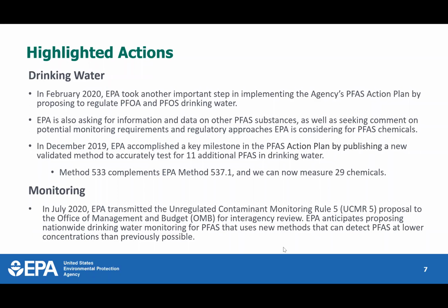Please do. I know a lot of you are water experts, but just as a point of background, the UCMR is under the Safe Drinking Water Act amendments in 1996. It requires that once every 5 years, EPA issues a new list of no more than 30 unregulated contaminants to be monitored by public water systems, and then the occurrence data that we collect supports our determination of whether to regulate particular contaminants that may be of a potential public health concern. So that's the background, and as Joe was saying, this is just the next rule, since it's been the 5-year increment.